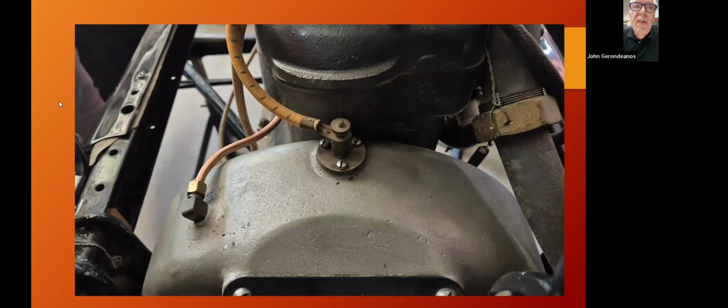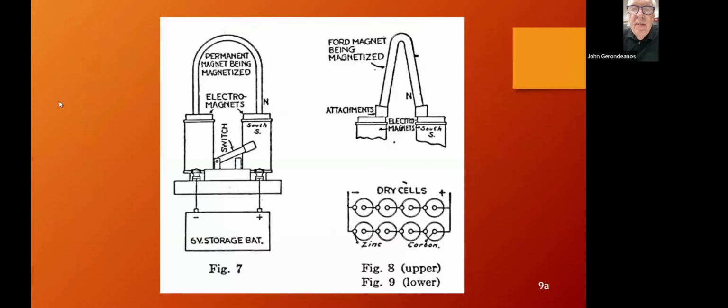And be very careful not to get it to connect permanently. You will melt the wire and you will also create other damage. Okay, and that's the 3 methods of doing Model T magnets. Okay, so let's go through some of the pictures and some of the videos.